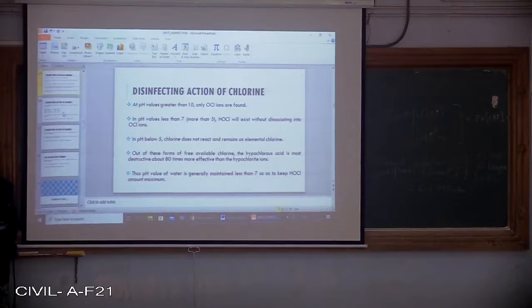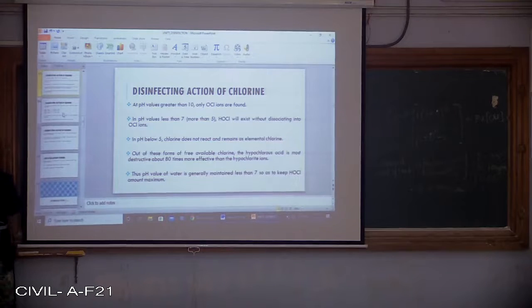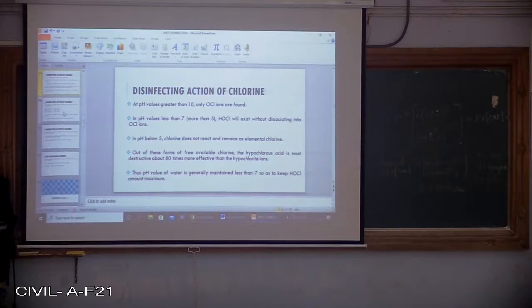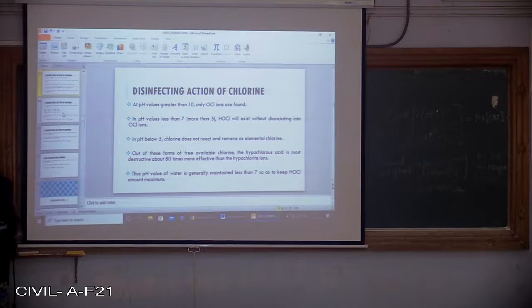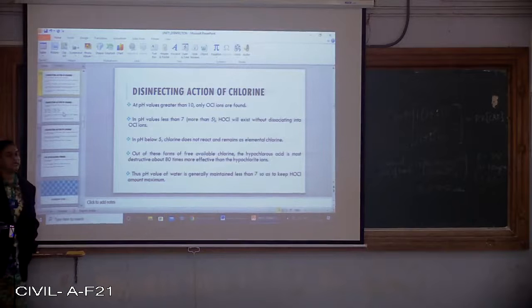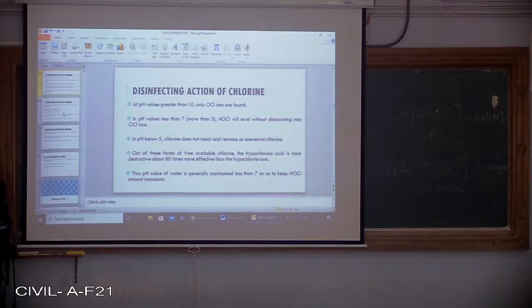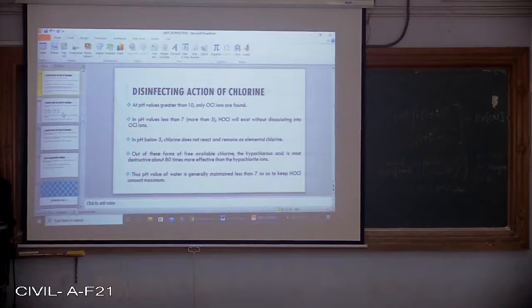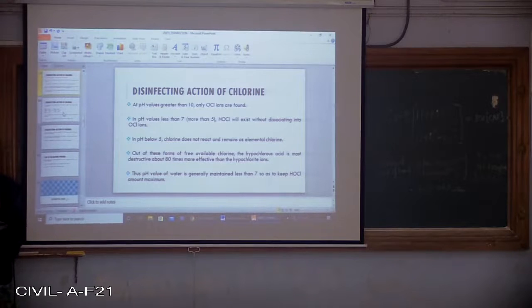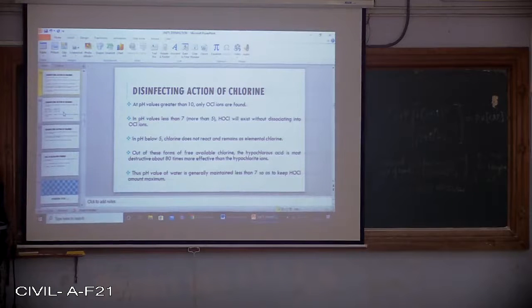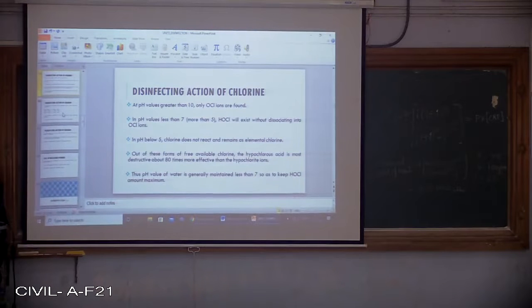Out of these forms of free available chlorine, hypochlorous acid is the most destructive, about 80 times more effective than the hypochlorite ions. Thus, the pH value of water is generally maintained less than 7 so as to keep the HOCl amount maximum.